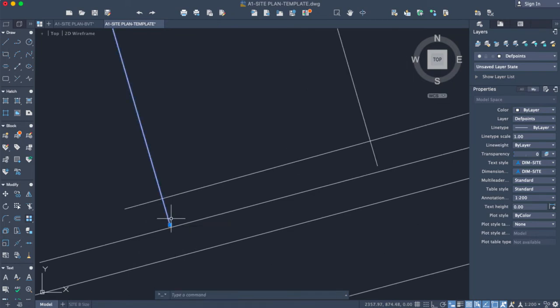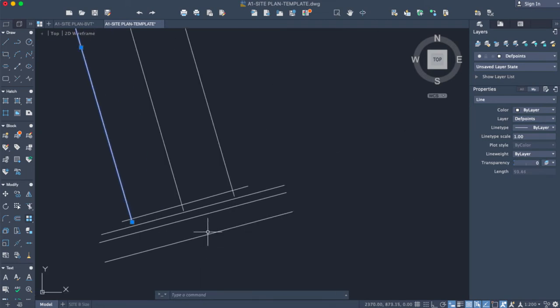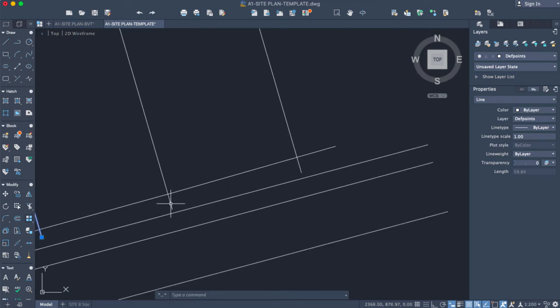You can shorten these lines to make it look exactly like what it is showing on the drawing. Make sure you're turning off the object snap when you're doing that, because it might not let you do that. Same thing applies with this one. You can just shorten it up by selecting it, and then without changing the angle, you can shrink it.